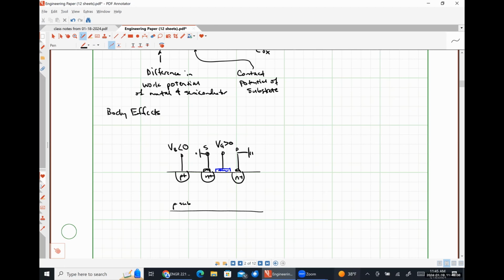Okay. So we have a PN junction around our implants, right? Because we have an N region in contact with a P region, we have a PN junction. If our body terminal is negative, is this junction forward biased or reverse biased? It's reverse biased, which means we're going to have a larger depletion region that we have to deal with, right?